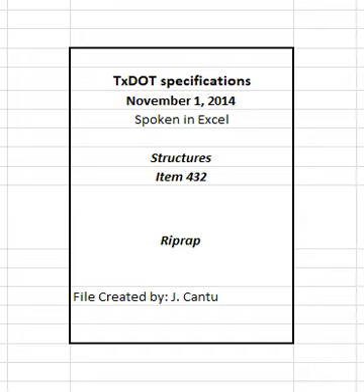3.1 Concrete riprap. Reinforce concrete riprap with 6x6, W2.9 x W2.9 welded wire fabric or with number 3 or number 4 reinforcing bars spaced at a maximum of 18 inches in each direction unless otherwise shown. Alternative styles of welded wire fabric that provide at least 0.058 square inches of steel per foot in both directions may be used if approved. A combination of welded wire fabric and reinforcing bars may be provided when both are permitted.